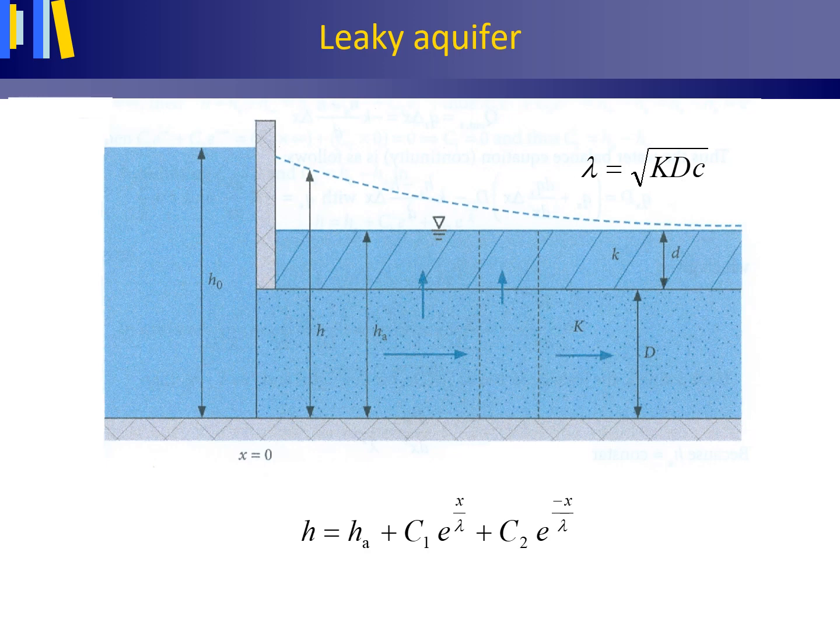In this example of het Hollands Profiel, the right boundary condition is taken at infinity. At infinity, the horizontal groundwater flow through the aquifer has diminished to 0, and the difference in hydraulic head between the aquifer, the dashed line, and the polder, HA, has also diminished to 0, and thus the upward seepage through the confining layer also is 0. We call this setup of het Hollands Profiel an infinite polder.